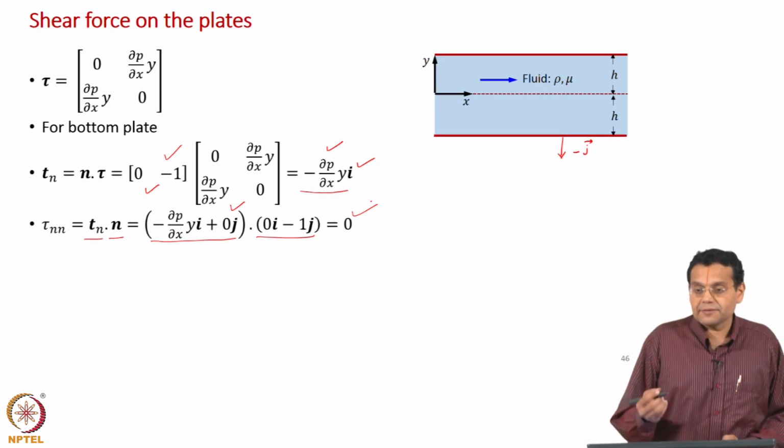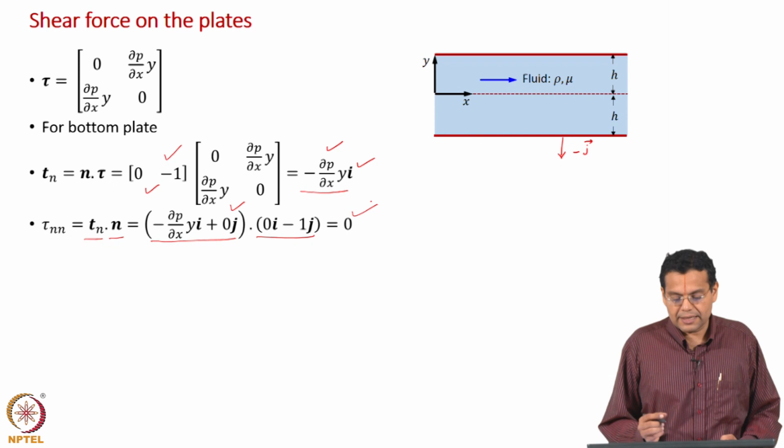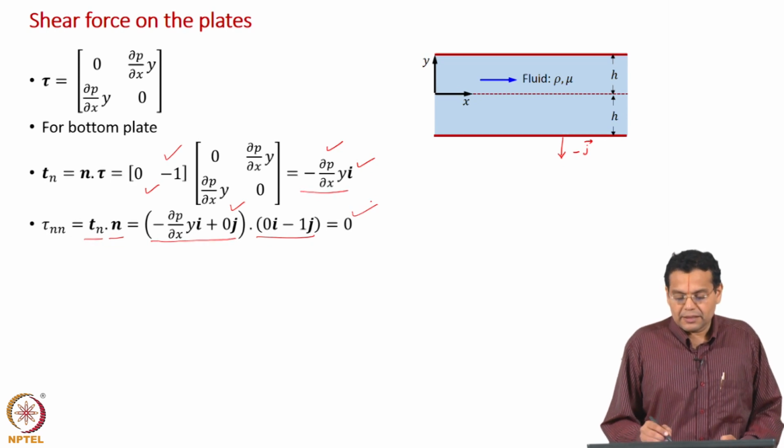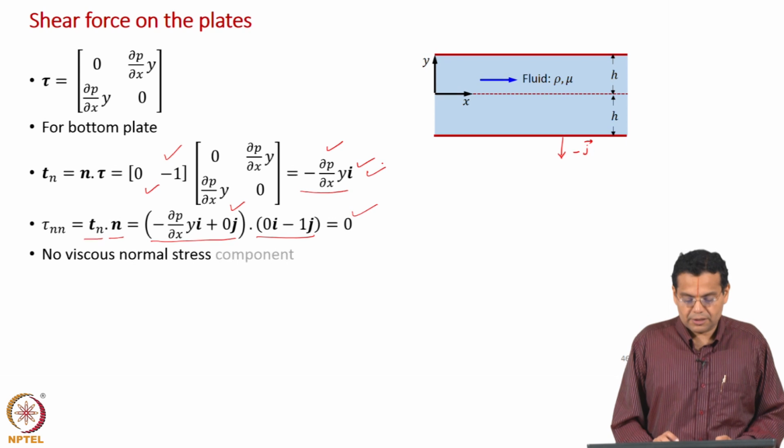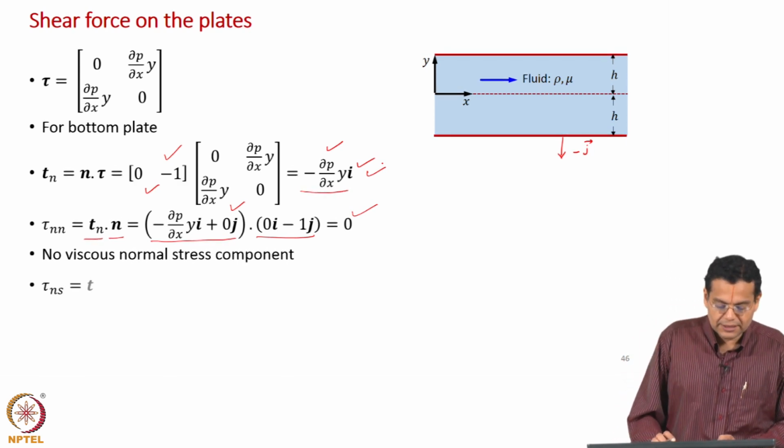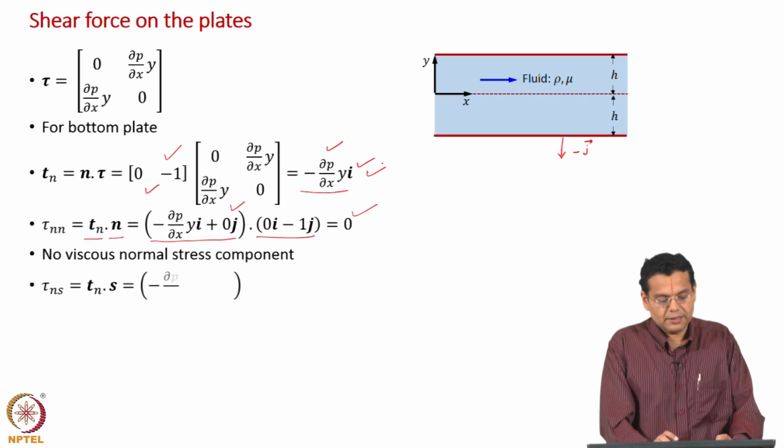As in the last case, we can conclude by looking at the stress vector that there is no normal stress component. So, no viscous normal stress component. So, let us find out the shear stress component.